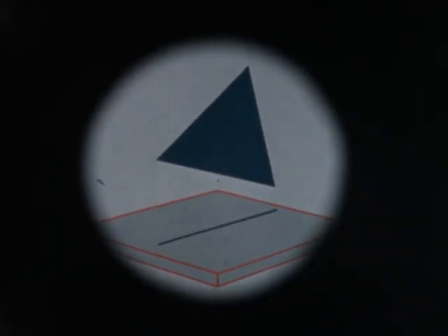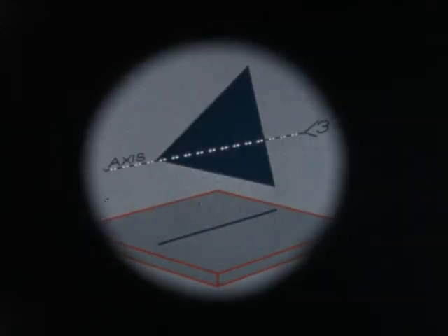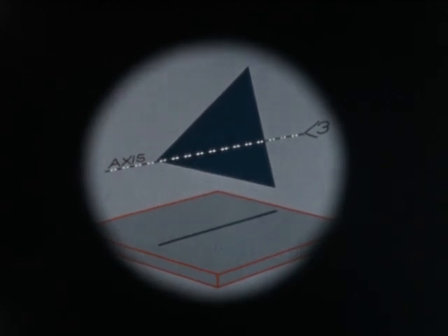The rotation of a plane surface follows a similar procedure. For example, starting with a vertical triangle, revolve it to a horizontal position about a horizontal axis on its surface. The axis here chosen through one corner of the triangle shows as a point when viewed from direction 3.